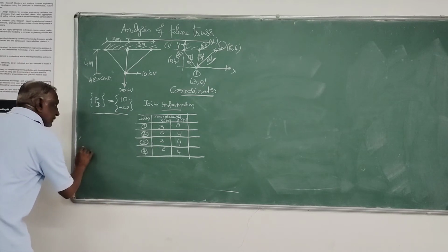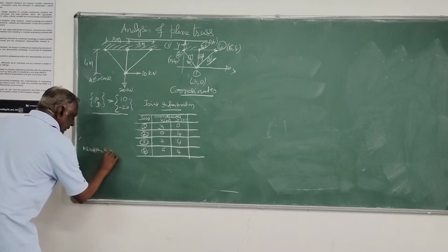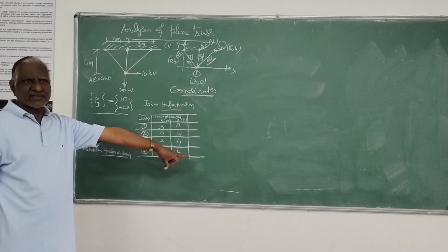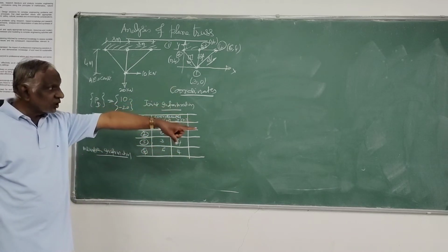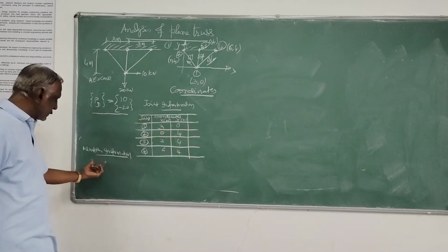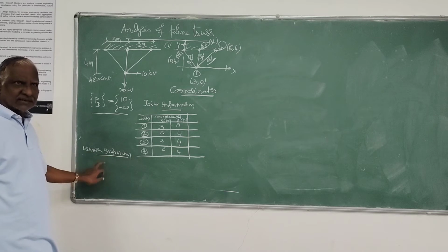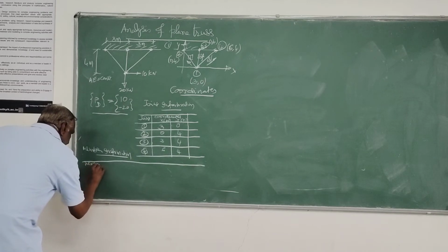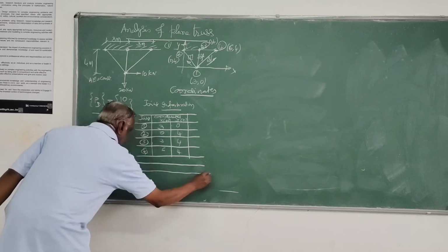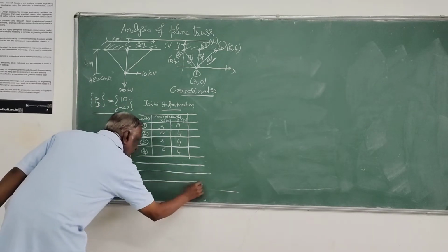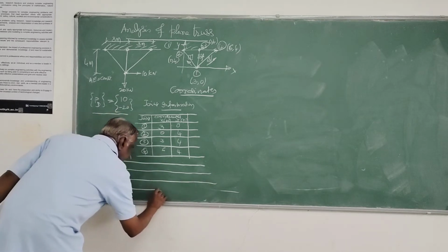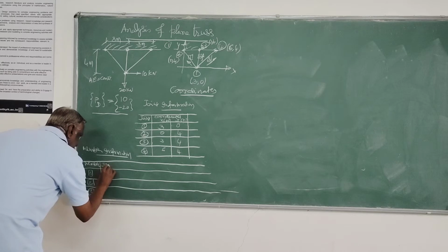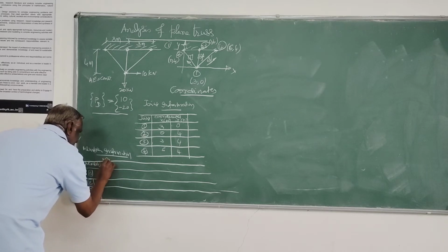Then we have to find member information. Why we have to determine this member information: all the element stiffness matrices Km that I have to determine are based on this. Similarly, for the global stiffness matrix, I also have to determine L and M, that is the member information. I will prepare a table like this. I will write member. There are only 3 members, 1, 2 and 3. Here Jn, that is the near end. Jn means near end.